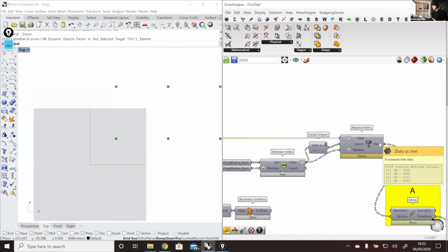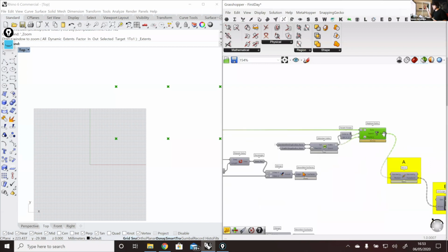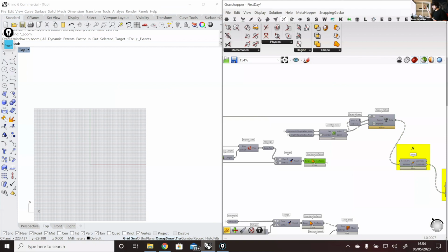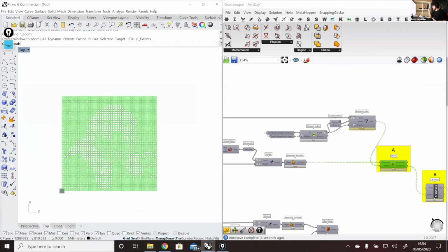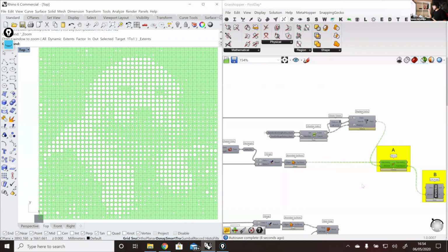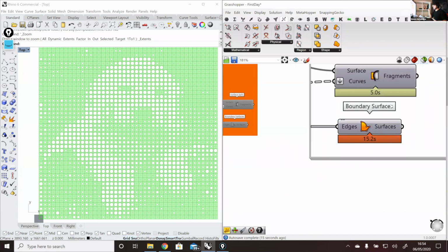And then I actually group them in the different branches that we have. So we have now, again, 4 branches. Branch 0 represents the standard radius, in this case, 10. The next one, number 1, represents the standard radius 20, then the next one and the next one. So here we have all of our points grouped based on their standard radius. And then with that, we can take our four surfaces here, which are also in 4 branches, and 4 branches here as well. We take this geometry inside here, and with that, we actually get our pattern, but it's taking 135 milliseconds instead of the 15.2 milliseconds that, for example, our boundary surface was taking.